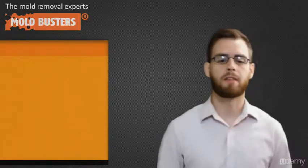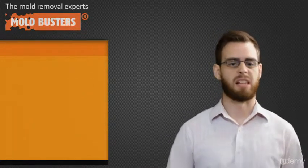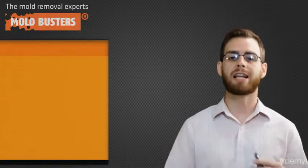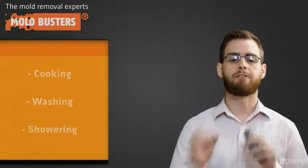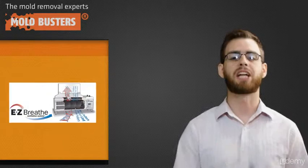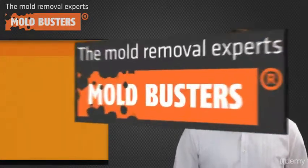Most mold problems are therefore the result of moisture problems, and these problems come from leaky pipes and roofs, flooded basements, cracks in walls and foundations, and also everyday activities like cooking, washing and drying, and showering. See, if a home does not have an effective ventilation system in place, the potential for both mold growth and poor indoor air quality increases.